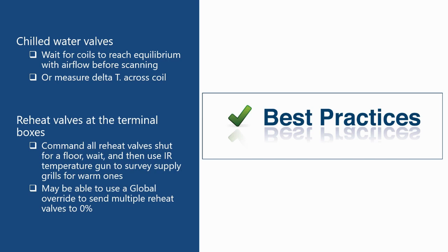And then finally, when checking and calibrating the span that's needed to properly drive the valves, be sure to always use the same instrument each time, as different instruments will rarely read exactly the same and could induce error into your calibrations. And then, of course, the measuring instrument that you're going to be using for calibration should be kept well calibrated itself. And this is especially true for pneumatic gauges, as they tend to be fairly inaccurate at pressures below 5 psi. And many pneumatic valves have spring ranges starting at only 3 to 4 psi. So just a half psi too much pressure may end up lifting a normally closed valve off its seat.